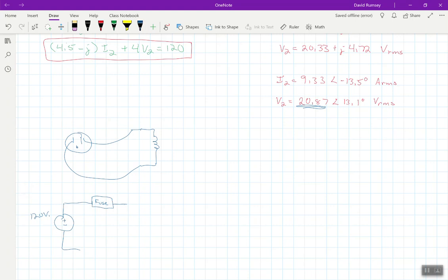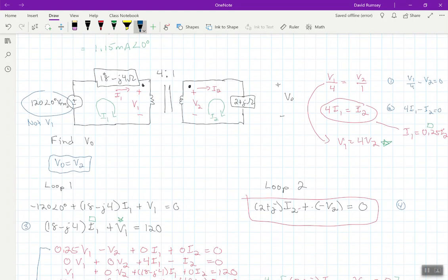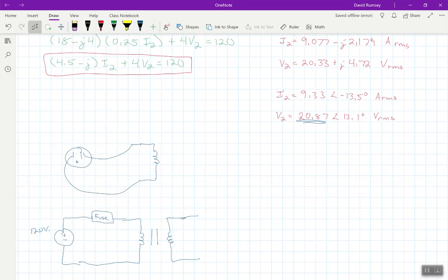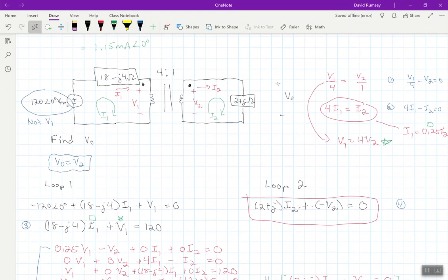And so what we'd really end up having is, well, we're assuming ideal transformers here, so we'd have our transformer here connected just like that. And so when we're connecting directly from the wall, we typically don't have this line impedance. So you might say, well, why did I include an example with a line impedance if we typically don't have that? Well, that's when we plug directly into the wall. If you're talking about distribution systems, power grids, transmitting power, there is absolutely line impedance that you have to worry about.